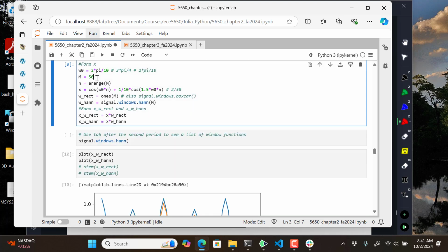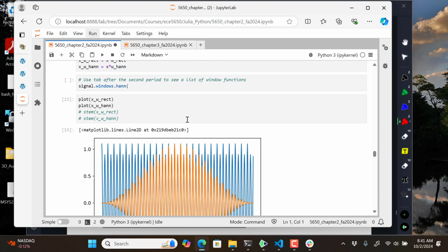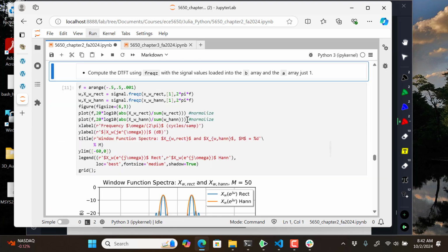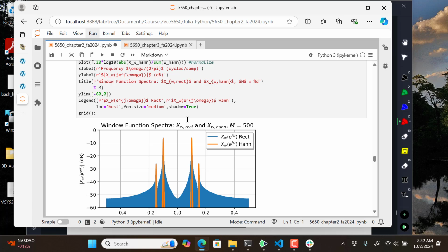So if we, again, take this up to 500, you still won't see it in the time domain. At least it's hard to perceive in the time domain. It's now very discernible in the frequency domain, even though it's down by a factor of 10. And what is a factor of 10? If it's an amplitude ratio of 10, that's like a voltage gain in decibels, so how many dB down should it be in the spectral domain? If I take the amplitude and drop it by 10, that becomes 20 log base 10, right? So it should be down 20 dB, and here we're at about -5, and here we're at about -25. Is that making sense?